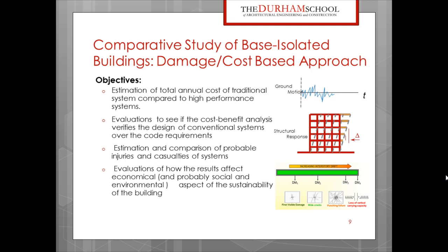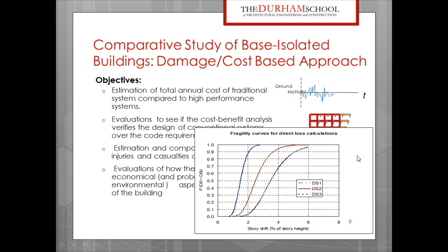With this, we assessed a building based on some ground motion, which can be an earthquake load, looked at the structural response, and then compared that to what we call fragility curves, which basically evaluates the amount of potential damage based on some performance index.